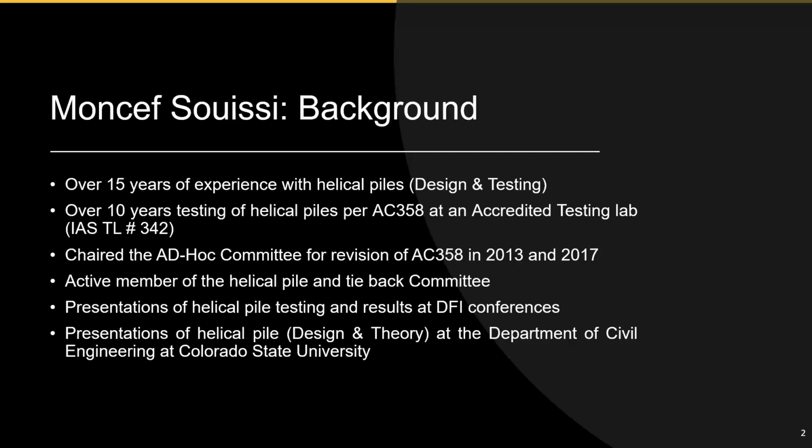IAS stands for International Accreditation Service. It's also a subsidiary of ICC. If you go to their website and look for testing lab number 342, you will see CTL Thompson. And the scope of accreditation is testing helical piles per AC358.